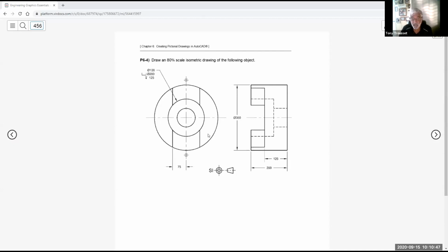The way you can tell is because the hidden line goes all the way to the top, to this point. So on the top view, wouldn't the left and rightmost parts be the highest then? No, the left and the right are the low parts. This part here and this part here are the low part.